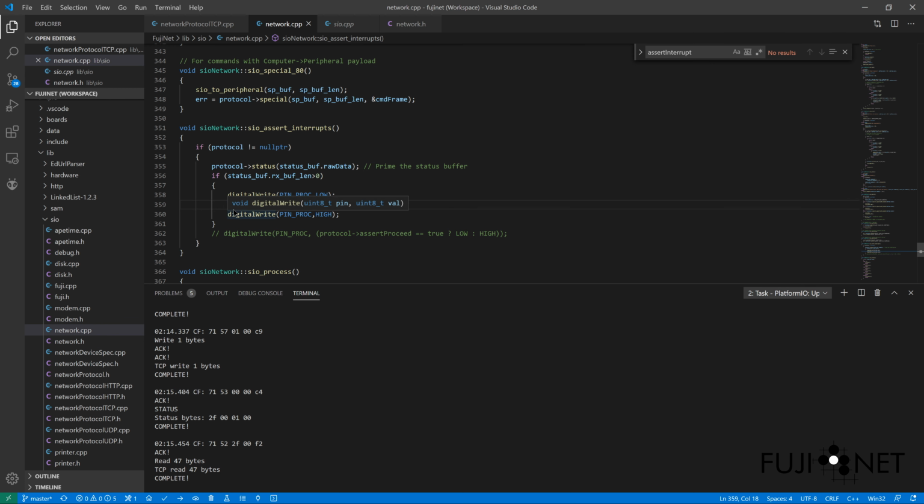Wait roughly 10 milliseconds. I'm actually going to tighten that up a little bit, and bring it back high again. This works because the PIA's interrupt handling is literally edge detected, and this allows the interrupt handler on the other side, on the Atari, enough time to react appropriately. Because what we're essentially doing is just giving it a little blink and saying, hey, wake up, wait for a second, come here, you need to handle something.